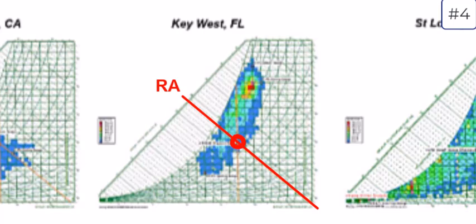Whenever the outside air has lower energy content, or enthalpy, than the return air, and we need to condition our supply air, we should be in economizing mode to minimize the load on our cooling coil with 100% outside air. In practice, it's difficult to measure enthalpy, so we would usually use temperature sensors to best estimate if we're above or below some high limit where it's no longer beneficial for an air handling unit in a given climate to stay in economizing mode, and the control system would change the outdoor air damper position to minimum.